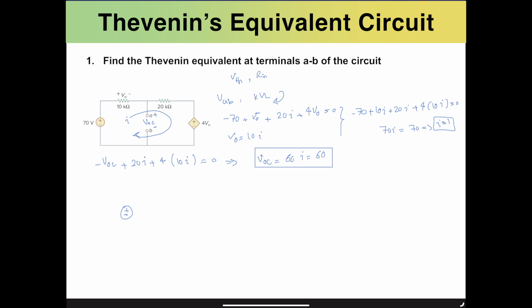So I would say the fictitious voltage source over here has the value of 1 volt, for instance. And I'm trying to find out what is the current that is passing through that, so I, and that is going to be through this 20K as well as this dependent voltage source for VO. On the left side, I have this 10K, and this short voltage source is automatically going to be short-circuited. And VO is again the voltage drop across this resistor.